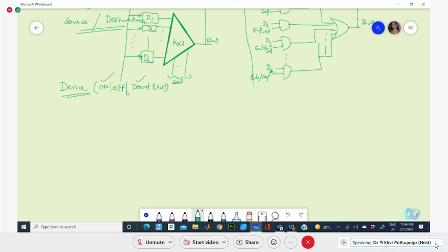If a device is there, if it is say a two mode device, it is on or off. But this buffer has the facility, in the sense, if you are using that buffer, that will contribute to the data transfer or contribute to the function. If it is not used, it will be as if it is not existing. It won't interfere into any of the circuit performance. There won't be any interference. Okay, this is what we call as three-state buffer.